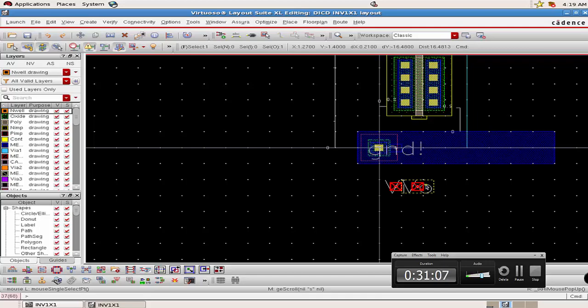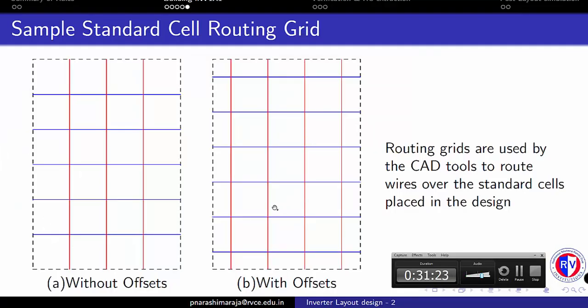So I will again show back the slide and we'll talk about the routing grid pattern, which is offset by half the pitch size. We have already seen that the major dots right now will be exactly at these intersect points. But as I said before, usually the power tool will follow this kind of pattern for routing grid. To get these positions, we have to look for our minor dots that are offset from our major dots by half the pitch size. What I really mean here is, when we try to overlap this structure onto this structure, these intersect points would be exactly at the mid places. So with that as our rule, we have to place our IO pins exactly at the center of these squares, where we will have 4 major dots on each corner of our square, right?